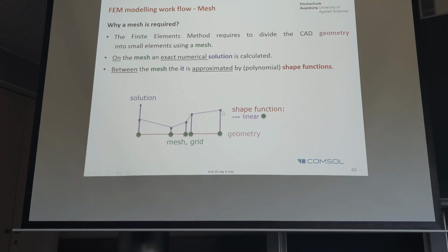And then the topic is how to handle the regions in between, because we don't have an analytic solution, so we only know the solution at those mesh points. The simplest way is linear. It's called the shape function, linear shape function. If you use a higher order shape function, quadratic, we discussed virtual mesh points. You don't see them, but this additional mesh point allows you to have a square function running through. You need one more point to calculate the curvature of the square.